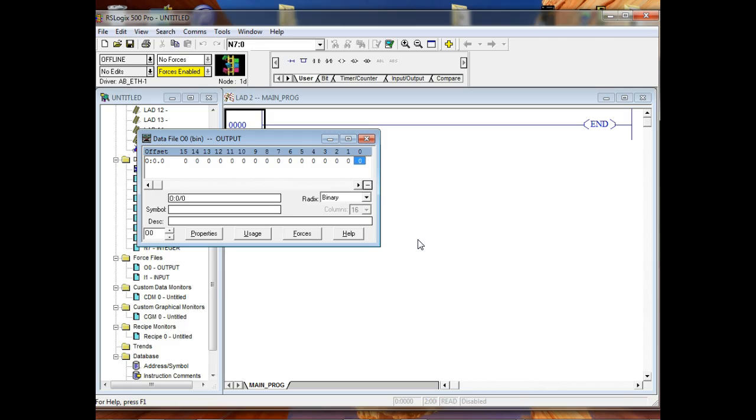Now you've got to be careful. They're running this guy on 120 volts down here, so don't touch him. So y'all need to keep the little door closed, right? This has got 1, 2, 3, 4, this has got 6 outputs. And that's what you've got. So what if I need 8 outputs? Yeah, you're screwed, right? You didn't buy the right number of fixed PLCs. If I run out of inputs or outputs on that guy, what can I do? I can add another module, right? You understand that?